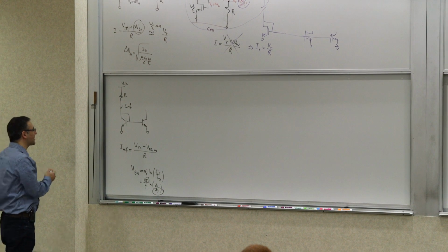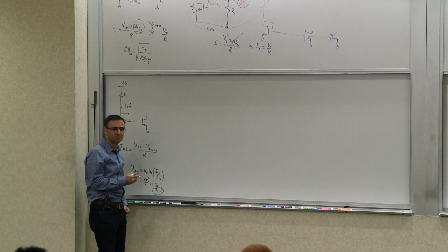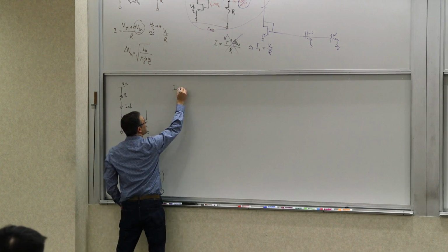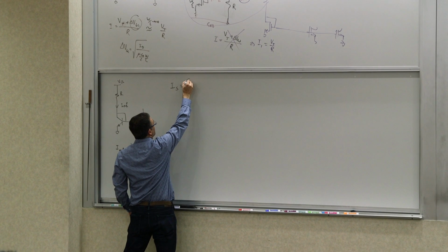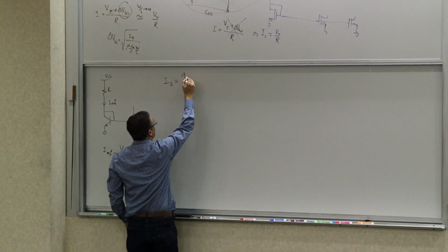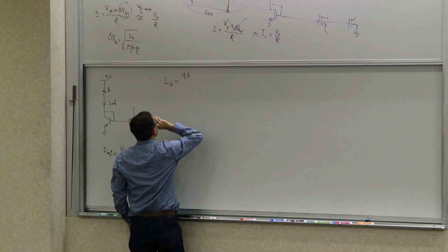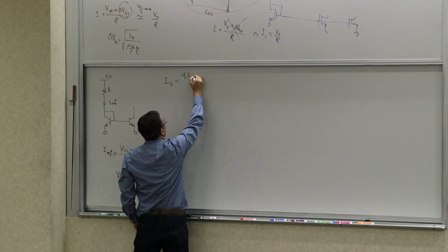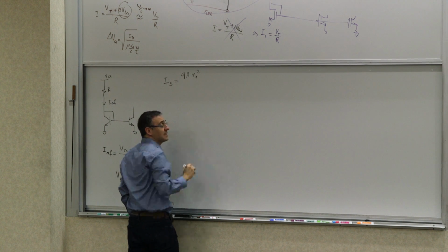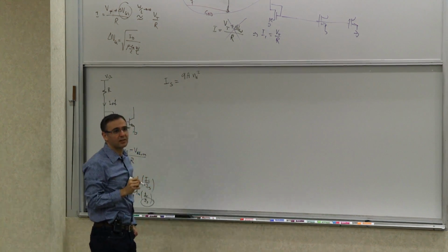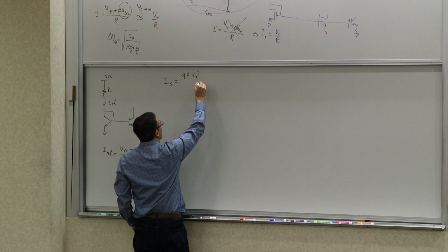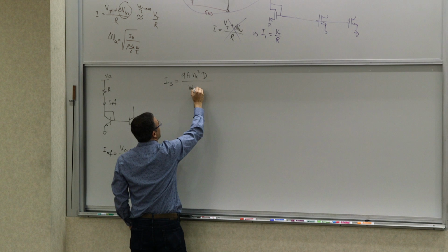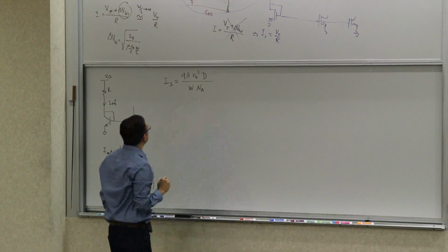So we need to really understand what the temperature dependence of this thing is. And to do that, we need to write an expression for the IS. So IS, the saturation current, is Q, the electronic charge, times A, the area of the emitter, which we kind of expected, times Ni squared, which is the intrinsic carrier concentration in an undoped situation, times D, which is the diffusion constant, divided by the width of the base and the doping concentration.